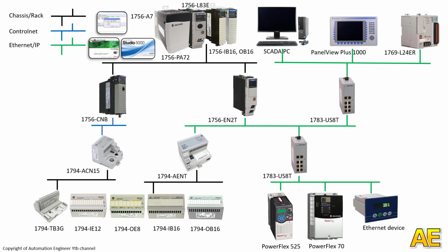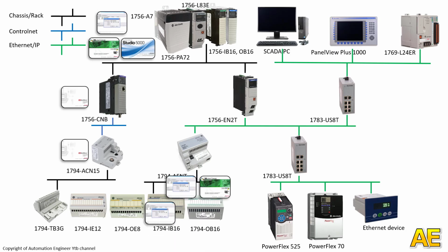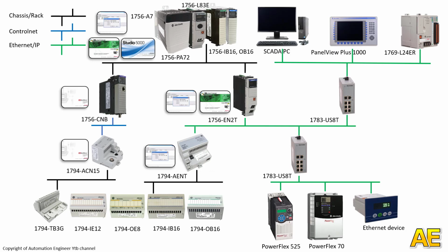For ControlNet configuration, we use RSNetWorx. For the Ethernet module and adapter, we also use BOOTP DHCP and RSLinx.